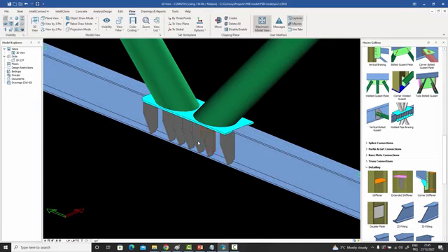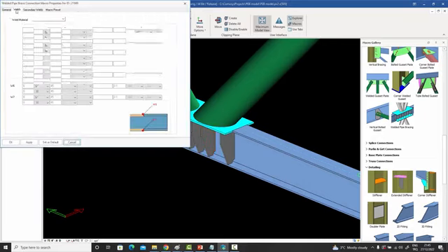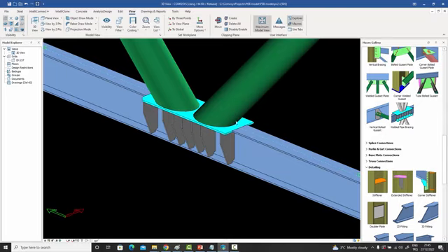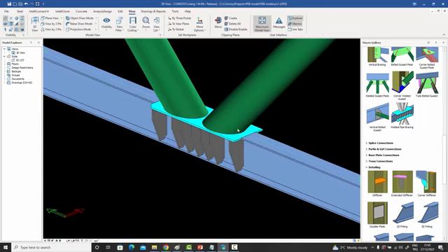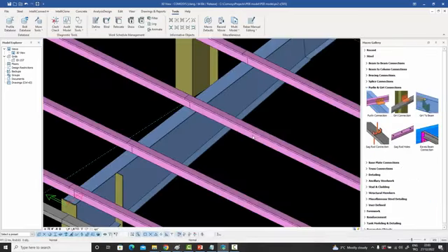The interface is complete, and we can basically have as many of those plates as we want, and we can give it whatever width that might be needed in the circumstances. But the idea is that you can just directly connect your welded braces to the beam, no matter how wide they are, because it's going to widen the flange anyways. And that's a very convenient way of creating this connection. This, like I said, once again, is very popular in the offshore industry.